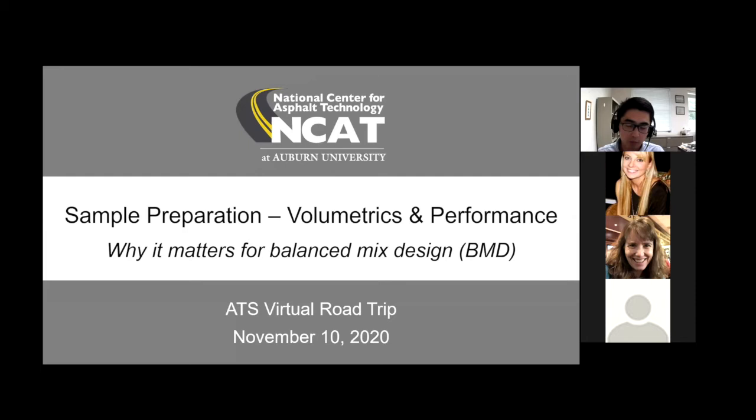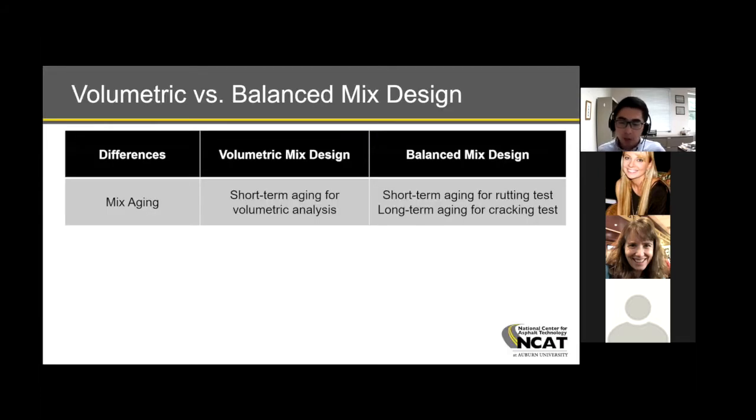Joe provided really good background information about what they learned from the NCHRP synthesis project. We found that report very helpful. It helps provide detailed guidance on how we can prepare specimens, not only for volumetric mix design, but more for performance testing as part of balanced mix design. So today what I'm going to present is a few case studies that emphasize the importance of consistency when we make specimens for performance testing in balanced mix design.